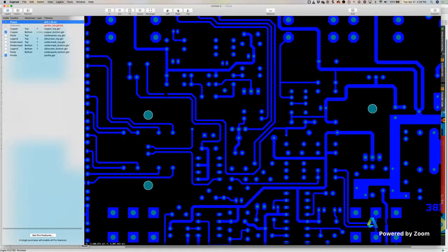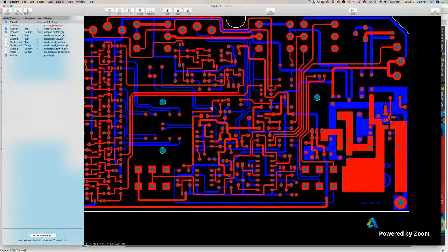Now, I want to make one observation because some people may be confused. Just in case, the solder mask is that material that is going to be covering your entire board, protecting all of your traces and all your connections. It's going to protect it, but it's going to be exposing all your soldering points, everything where all the components are going to be soldered. The way Eagle exports that file, actually, I think all applications do it, not only Eagle, is that they provide a negative image.